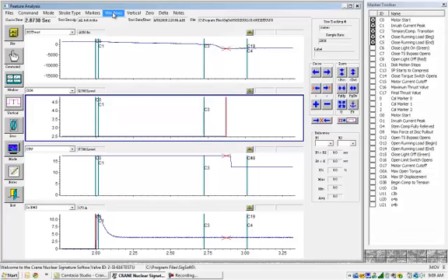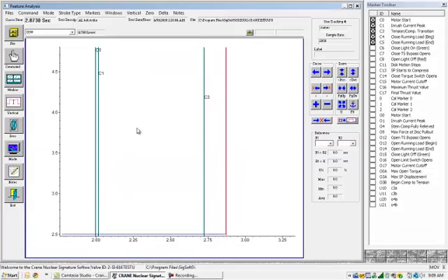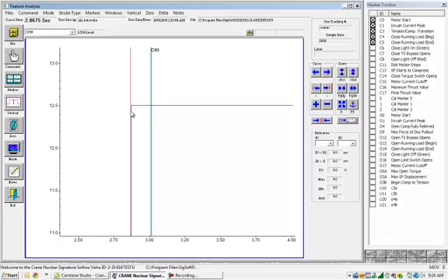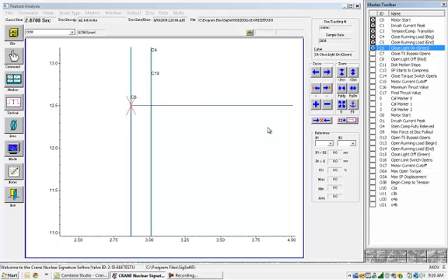So let me make this one window so you can see it. Okay, we got a trace coming, goes here. We got 10-volt trip, and then we have a 5-volt trip here. Okay, actually that's 12.5 right there. Okay, so right here, this would be the green and the red. Excuse me, the black and the red happening at the same time. So the green light on is when the valve goes to mid-stroke by indication.